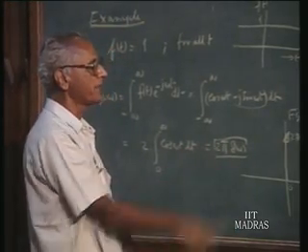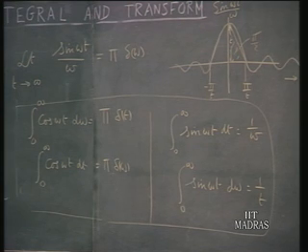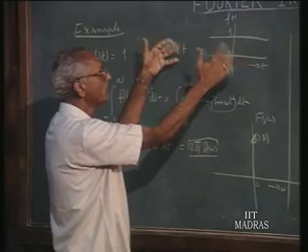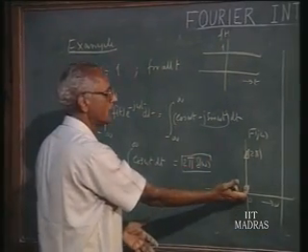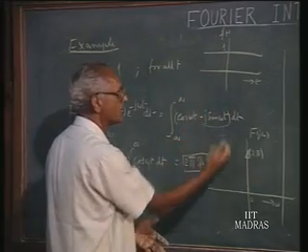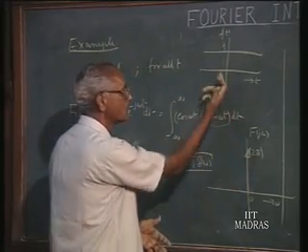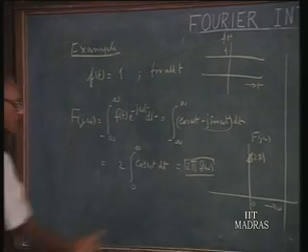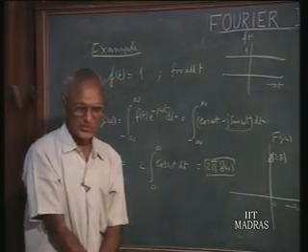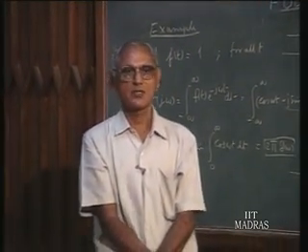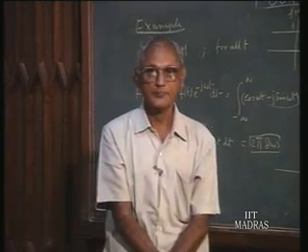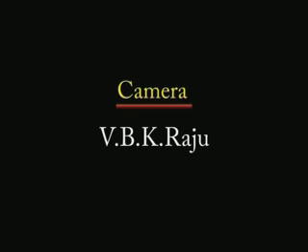We assume these results, and making use of these results we tried to find out the Fourier spectrum of a pure DC quantity and came up with the result, which perhaps could have been quite obvious, that this particular signal has only one frequency component, and that is DC. It becomes a line spectrum once again in the Fourier transform also, but there is a coefficient which is non-zero, therefore the coefficient density has to be infinite. Therefore we have a delta function, and the coefficient density is 2 pi delta omega, and the density occurs at 0. And so we can expect that when we talk about periodic functions, in the line spectra, the magnitudes are going to be infinite involving delta functions. More about this in the next lecture.